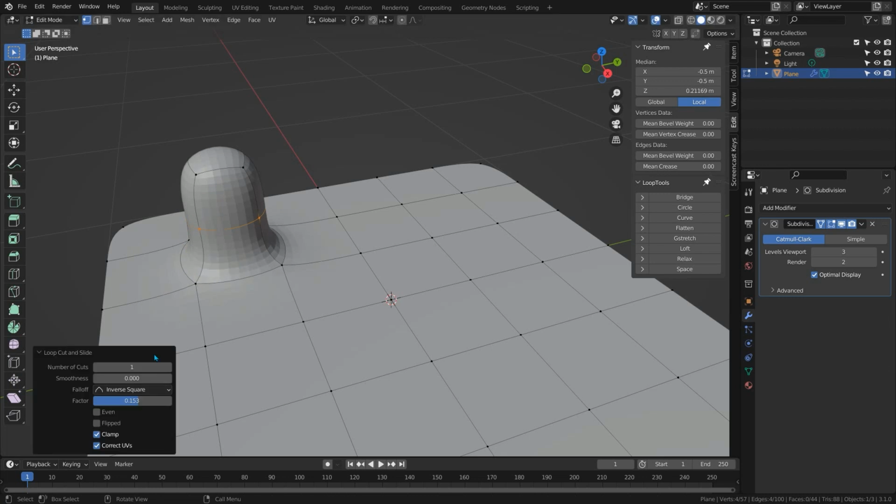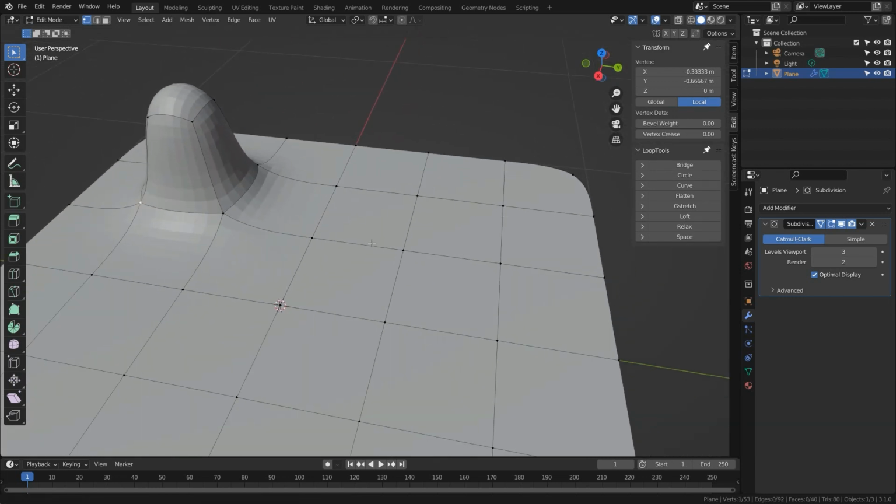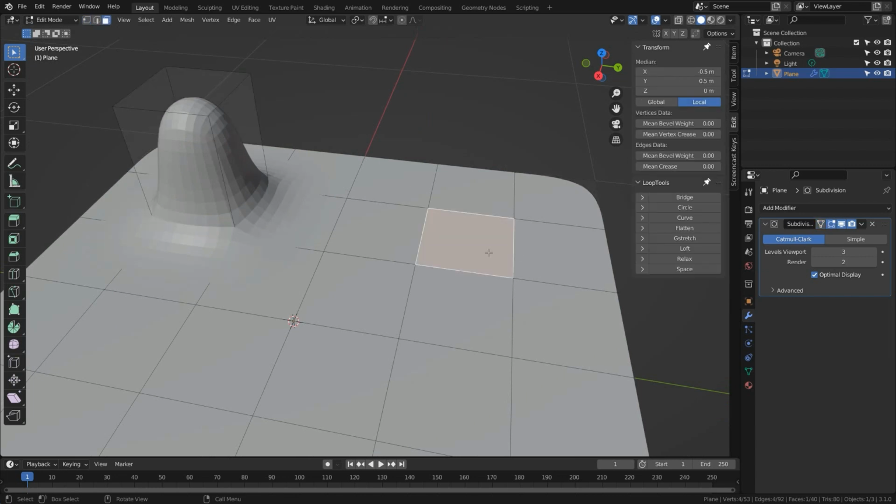And the curvature is still spreading out all the way to the edges of the next faces. We have no good control over this extrusion at all. Now the explanation for these problems was long, but the solution is really short and simple. Now I'm going to select this face, but before I extrude it, I'm going to press I to inset it.